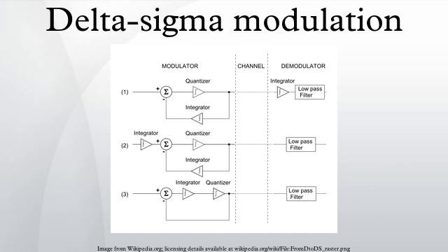The above description shows why the impulse is called delta. The integral of an impulse is a step. A 1-bit DAC may be expected to produce a step, and so must be a conflation of an impulse and an integration. The analysis which treats the impulse as the output of a 1-bit DAC hides the structure behind the name and causes confusion and difficulty interpreting the name as an indication of function. This analysis is very widespread but is deprecated. A modern alternative method for generating voltage-to-frequency conversion is discussed in synchronous voltage-to-frequency converter, which may be followed by a counter to produce a digital representation in a similar manner to that described above.